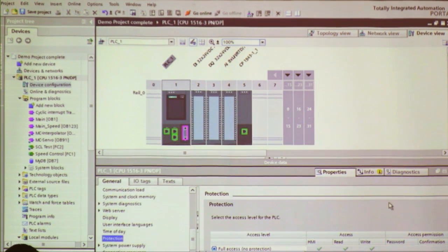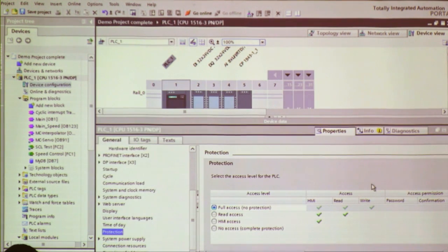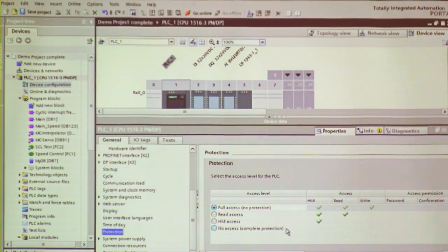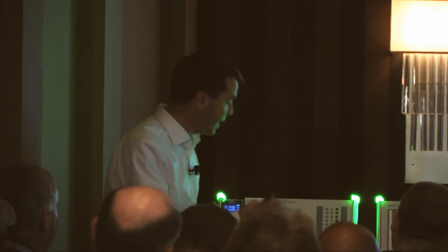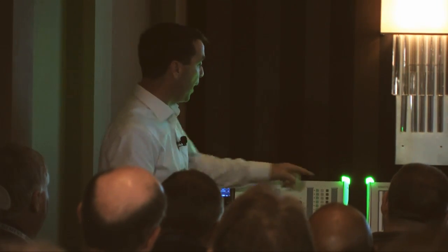And those of you who are familiar with our software probably already know, we always had read and write access protection. But what's new here is they've added a new fourth level of protection, because with the current systems, even if you have a know-how protection, or read-write protection, so nobody, if they try to access the PLC with the PG or whatever, they're prompted with the password and they can't change any of the code. You can set that up today. But if an HMI was connected to it, you can go to the HMI and you can change data on the data block all day long.